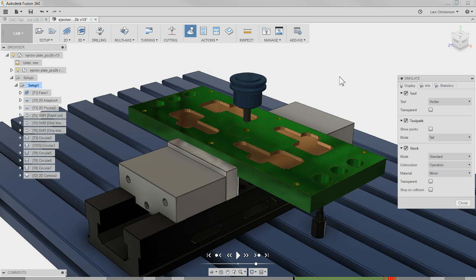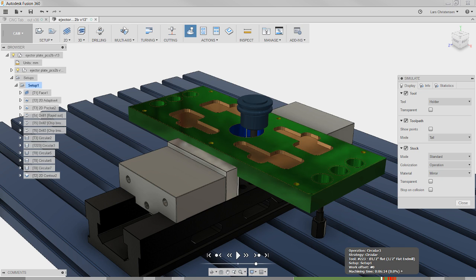All right, moving on. So go down here and select, and it will jump right to that tool path there. Now you will see, as we're looking over in the stream, some of you guys already know what this means. See all these red lines down here? That shows me that there are some collisions. And if you hover over them, it shows here collision 1, shaft collides with stock. So read this because it gives you some information. The next one, circular 3, collision 6, holder collision with stock.